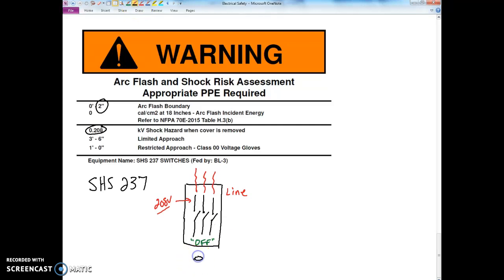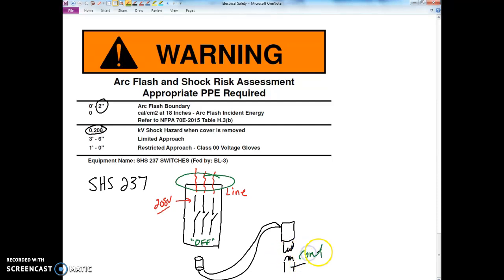Now you guys have a plug and a cable that goes over to a switch on your panel board. That switch then goes to a transformer, and the incident energy continues to go down from this point. I am actually talking about this point right here. And so the incident energy continues to go down as you get over to your control panels. On the control panels, with this transformer being 208 to 120, we're down here at the 120 volt level, which, if we measure voltage, we have to have hot gloves. We're greater than 50 volts.